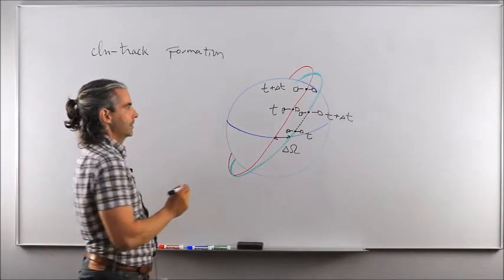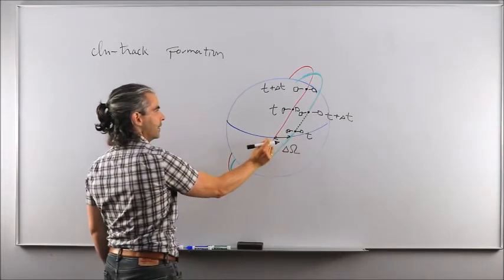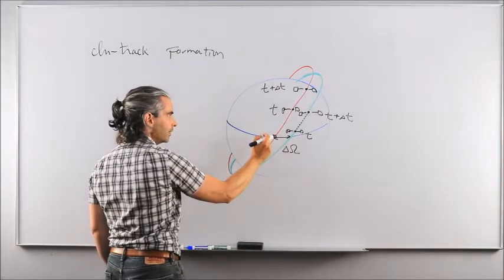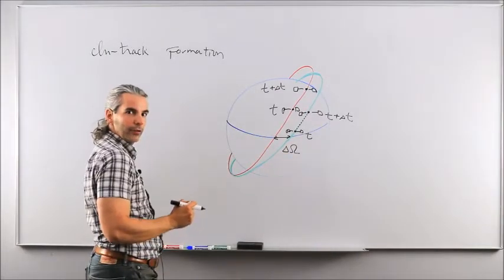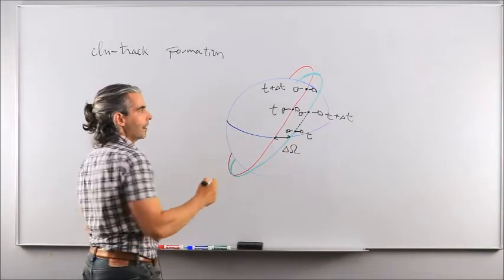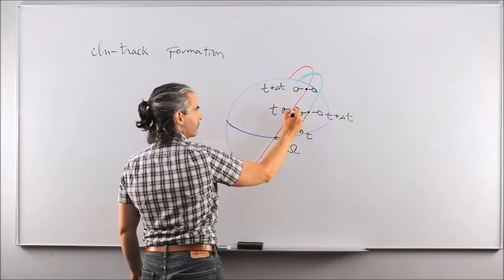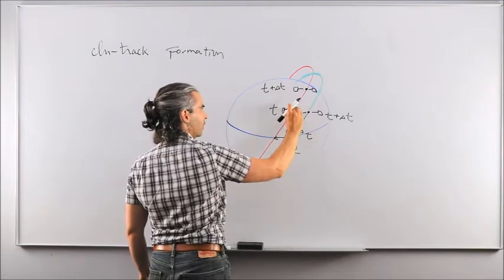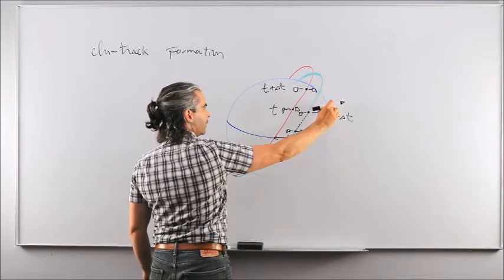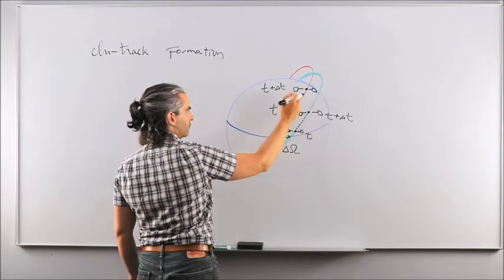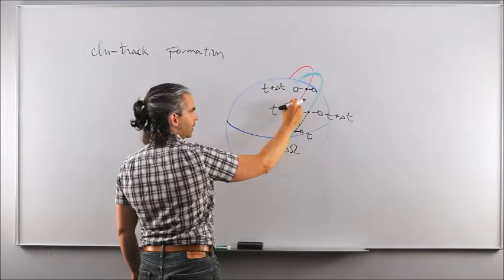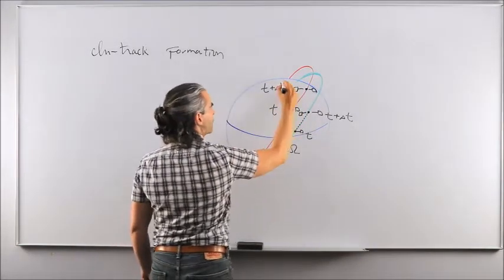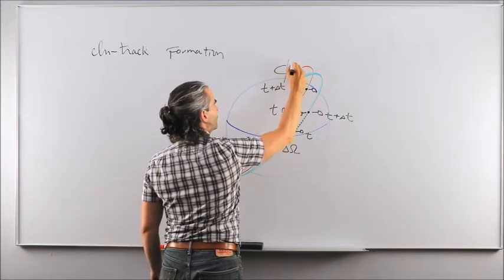Because if they would share the same RAAN, yet spacecraft 2 behind spacecraft 1, it would be impossible for them to fly over the exact same spot. Because spacecraft 1 would fly over Ottawa, and whenever spacecraft 2 would reach the same latitude, well, Ottawa would be right here. So here we could look at, I don't know, somewhere in Saskatchewan, for example. Because again, the Earth spins underneath the orbit.